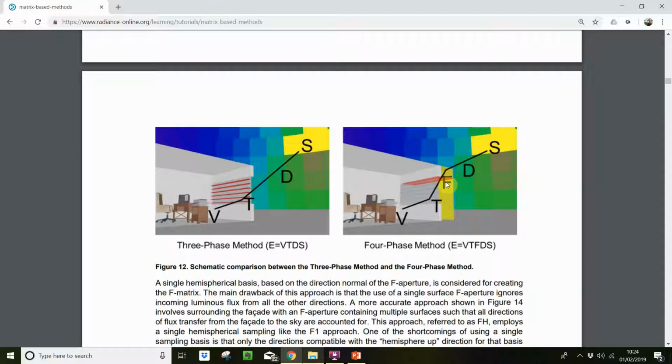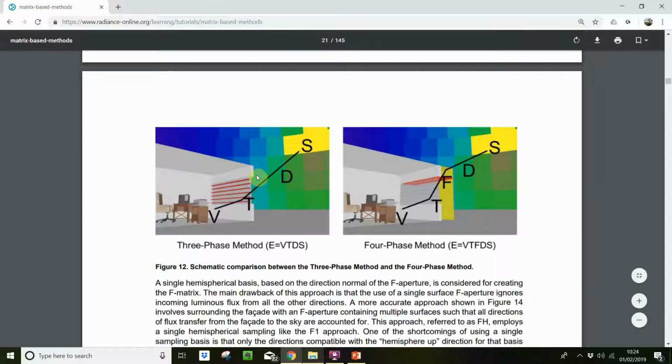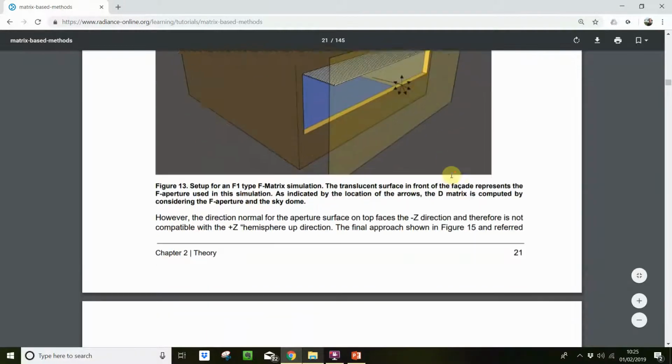Well, let's imagine that fenestration looks like this. It has that level of detailing. We're back to the dilemma that we need an accurate calc to move that through. It's not going to be good enough to say we have an accuracy of like a meter, and let's say that's only half a meter anyway. That's not going to be very good. So we could pick up the shadow patterns, but not the inter-reflected light. So the fourth phase actually adds another phase, and it is an isolated calculation where we can control the light occurring in this area here.